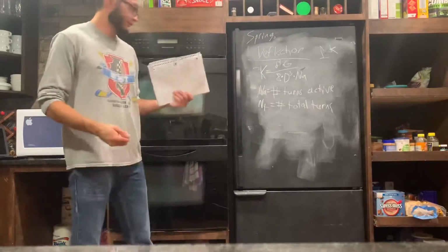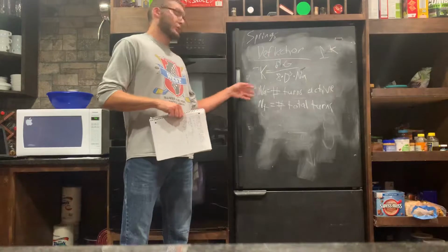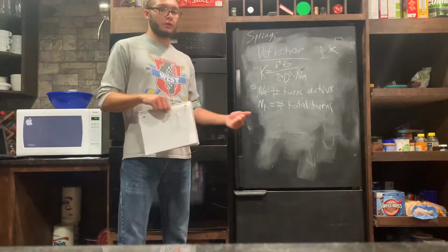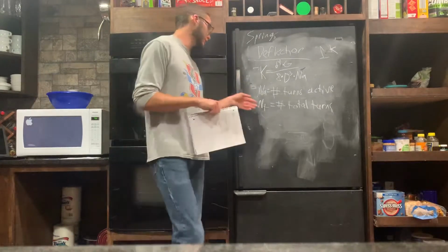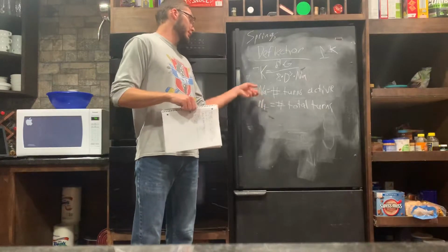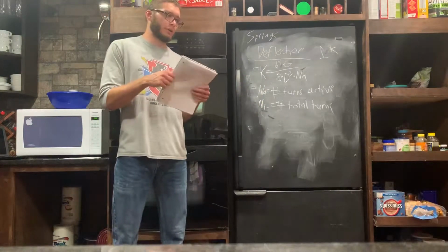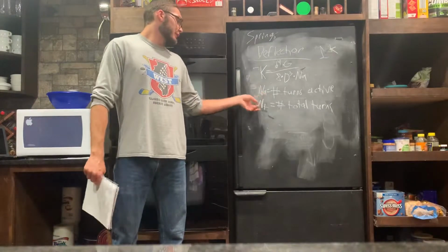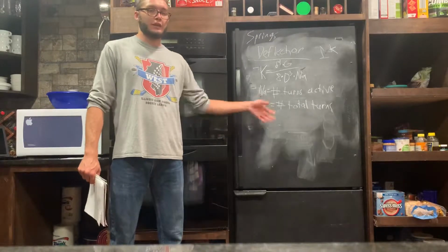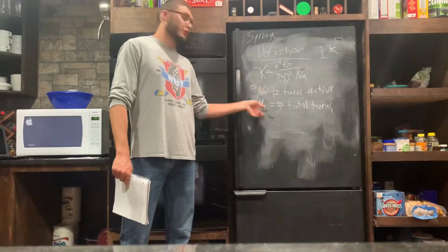And NT is usually found using a graph, or we can do it the other way, using the charts, which again reference closed end, grounded, closed end, not grounded, open and grounded. We can solve for these either way. If we get the total number of turns, we can go back and plug it in. For example, for 12 turns, NT is equal to NA plus 2, or for a closed grounded spring, NA plus 2 is equal to NT.